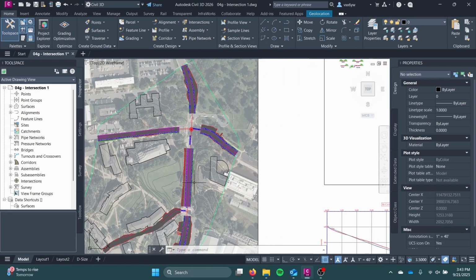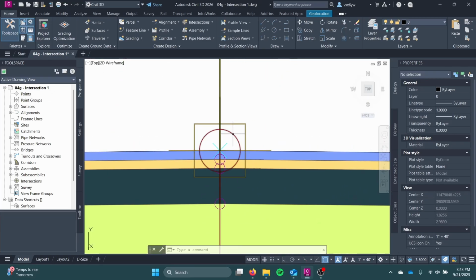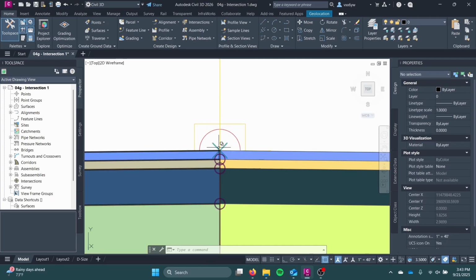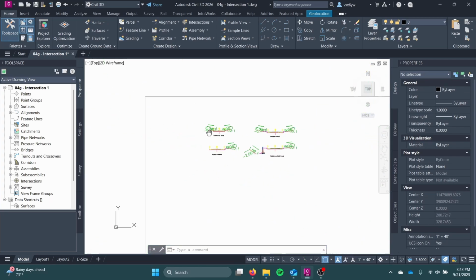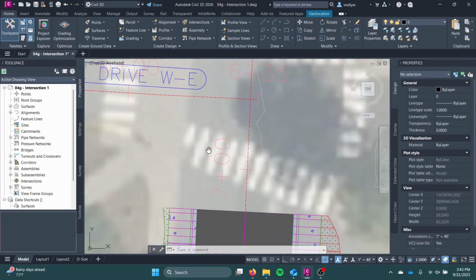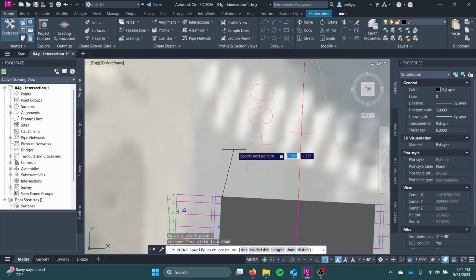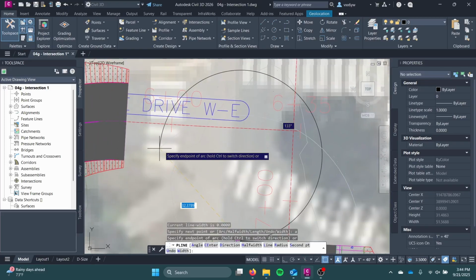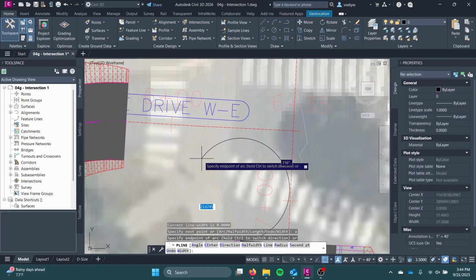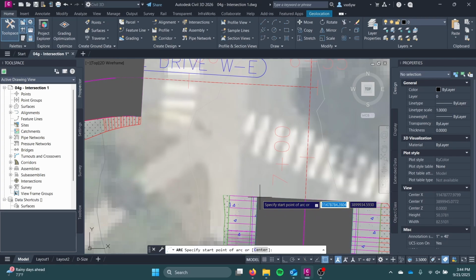If you recall us talking about all of the links and points on assembly, like these points and how Civil 3D will join up, it'll create multiple sections and then join those sections with lines that go through similar points. It's actually possible to assign those lines yourself. So what a lot of people will do, professionally, is come and create a polyline, and they'll specify their own. The roadway is here, and the arc looks like this. Oh, that is huge. But they'll actually draw these lines themselves.